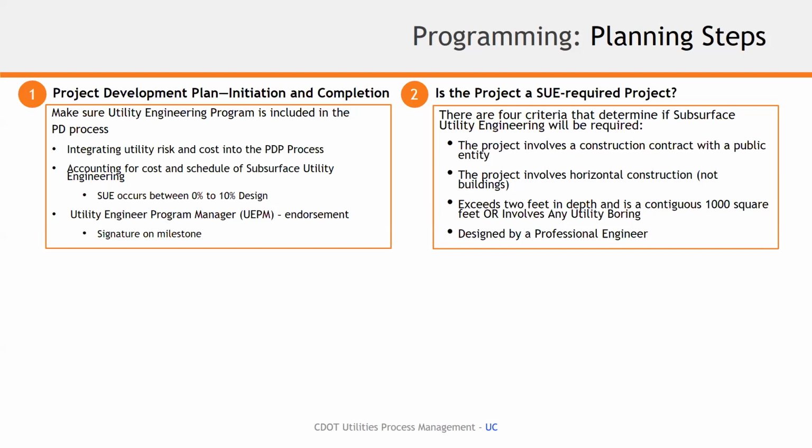So you might have a project that doesn't require open excavation, but does have subsurface excavation like a utility bore, and so that will count as the criteria for number 3 there, in lieu of the surface disturbance and excavation requirements of 2 feet in depth or more. So just keep that in mind as you look at the criteria related to your project in the future.